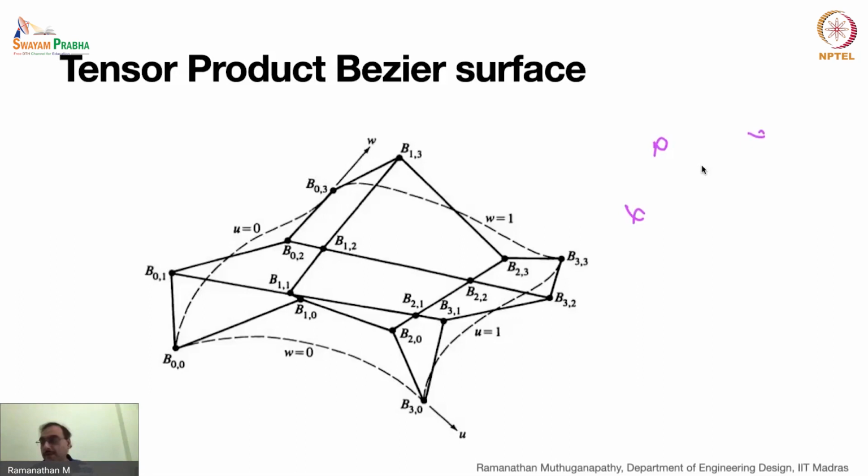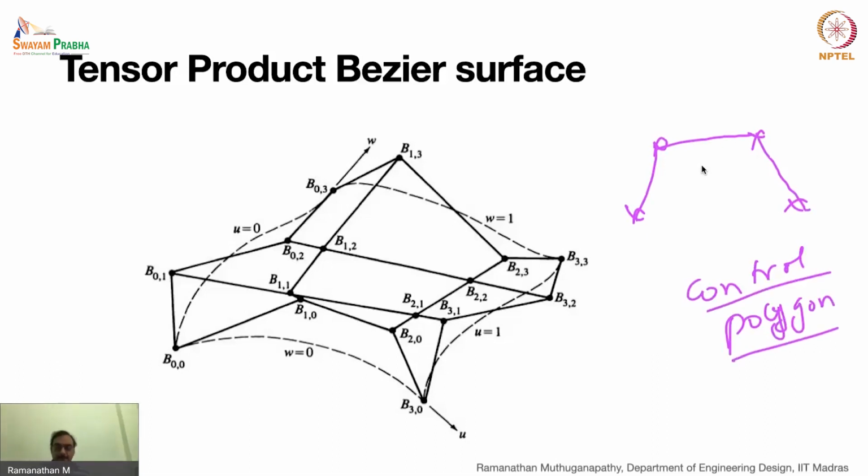Okay, I have a set of control points, and then if I join them, you may or may not close it. This is called a control polygon. Now see if this picture is somewhat related to that in terms of course, surface. So what can you say about it? So control polygon, just that we are having points outside the two-dimensional surface. No, but even your 2D polygon also can be a three-dimensional space curve. We didn't talk about space curves in Bezier, but you can have the same three coordinates for each of V0, V1, V2, V3, X0, Y0, Z0. That also could be a three-dimensional one.